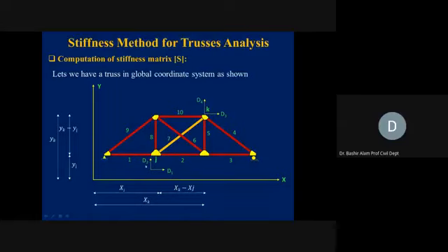So that will become our D1, and for that D1 we will call DM1, because we need to now differentiate between this D1 and the member axis, which is DM displacement along the member axis now. So this will become DM1, and perpendicular to this, which is the local y axis of this member, that will become our DM2. Similarly, at this joint K now of this member 7, along the length of this member, it will become DM3, and perpendicular to this, it will become DM4. So those are the displacements now.